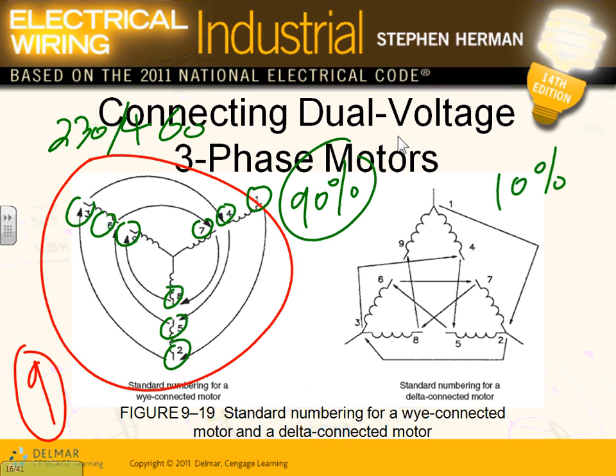I like percentages, so I'm going to throw out 10% of the time you have a delta motor. Delta motor, high inrush, high torque, you can get out of them. But the current inside the winding is high. That's why if you put a delta, the current that goes through the delta is going to be high, guys. So meaning, who cares if the current inside the coil is high? The coil is going to be big to handle the current, right?